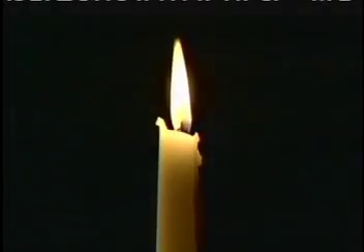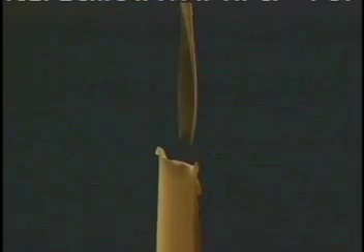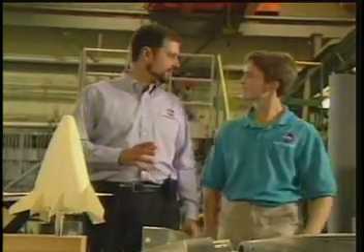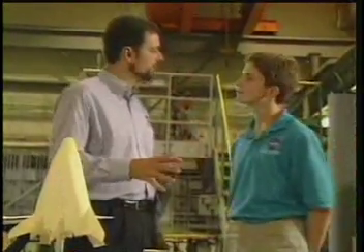You can see this natural process by looking at the smoke after you blow out a candle. After you've blown out a candle, you'll notice that the smoke near the candle rises smoothly. That's laminar flow. But farther away from the candle, you'll notice it becomes rough and irregular. That's turbulent flow. Normally, we think of laminar flow when designing aerodynamic shapes. We want the air to flow smoothly around them.